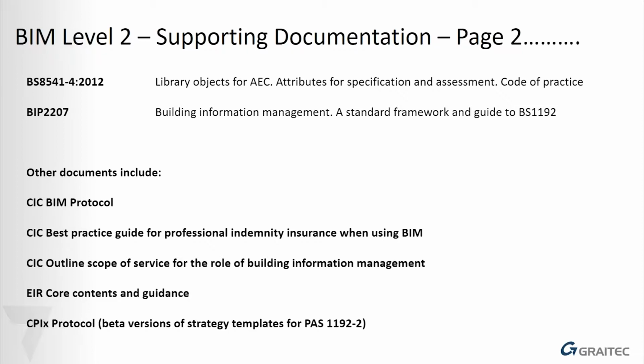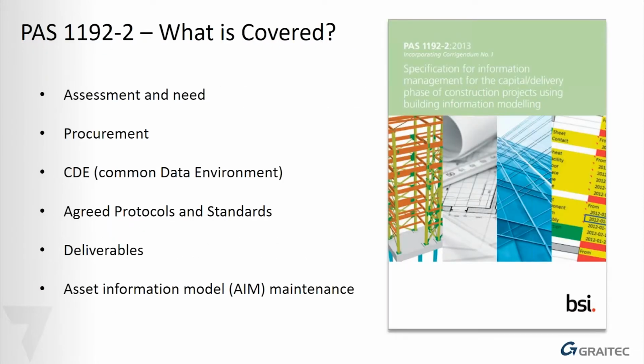We then have these PAS documents. There's a lot of PAS documents. There's PAS 1192, 1, 2, 3, 4, and now 5. These will describe how a BIM process works, so everything from taking the project from day 1, getting the supply chain involved. There's some good information in PAS 1192.2 on how we start to get everyone involved, all the way through to PAS 1192.5, which is more related to the way that facilities management works. And again, more documents moving forward as well.